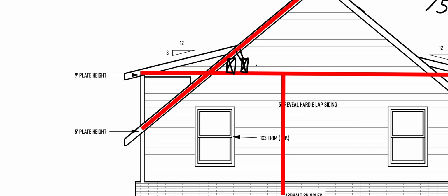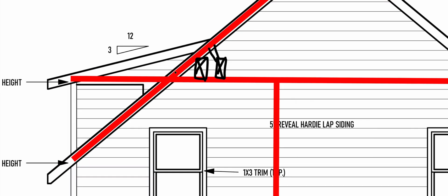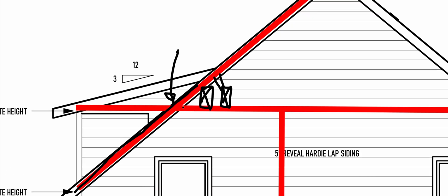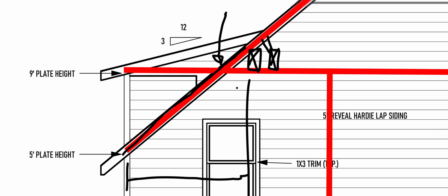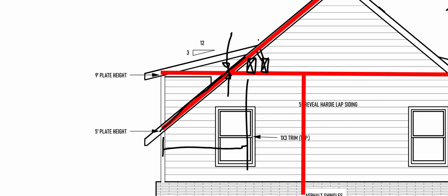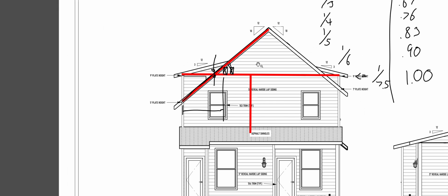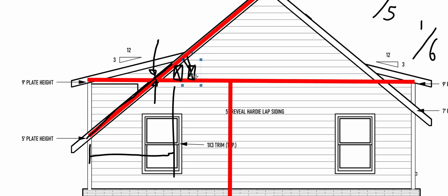The point is, I'm going to pick up the weight and support the rafter along here so that when we add the extra weight from the ceiling right there, even if it's just a little bit, that weight's not going to make a difference in the effective span of the rafter, which is here to here, right? Adding a little bit of weight close to the end of the span doesn't make hardly any difference. So that's what I'm going to do, and that's how I'm going to solve this particular problem.